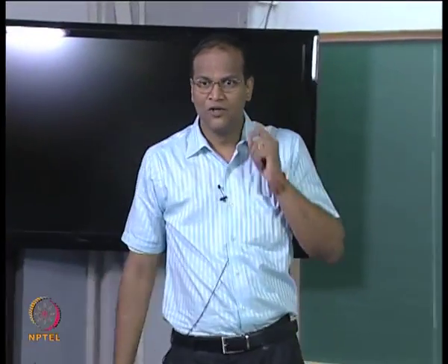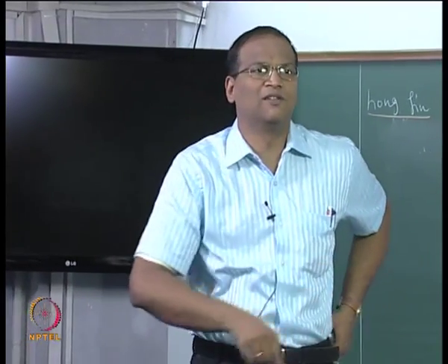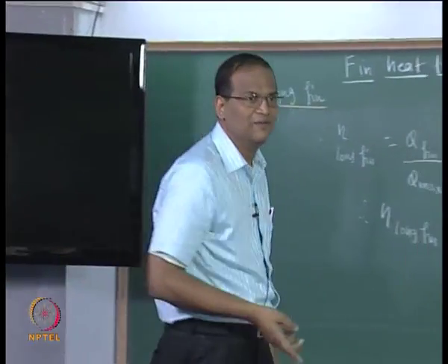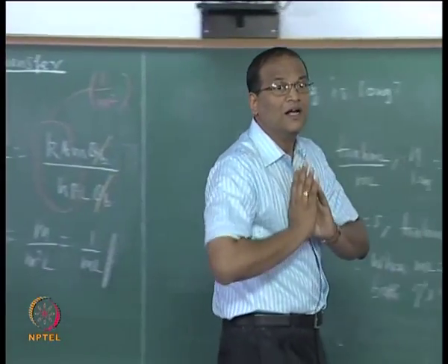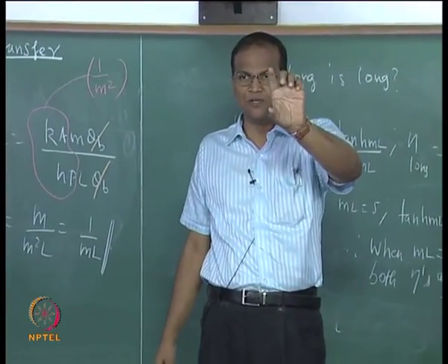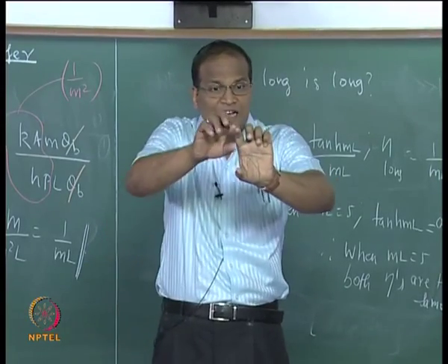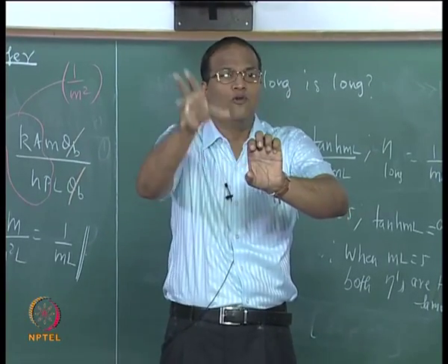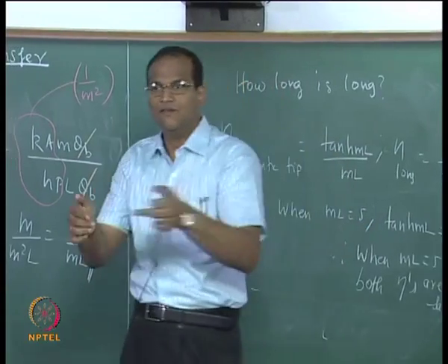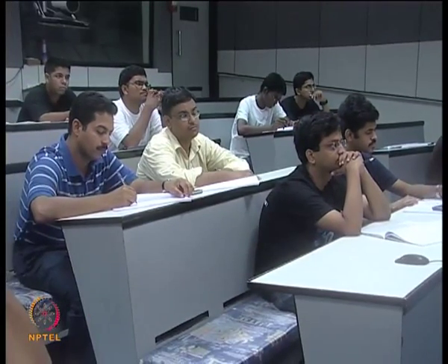Are you getting the point? So the general governing equation cannot be used to derive the one dimensional fin equation. We have to do it separately because we are lumping the heat transfer across the y direction, because we are saying that the thickness is so small that there is no temperature distribution in this. If there is no temperature distribution but there is convection taking place, how do we factor that in? hP dx into theta, we put it into the equation. Is it okay? All right.